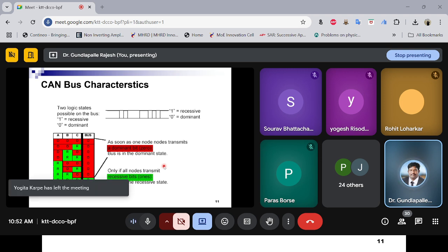So when it is receiving, for every 5 bits it will see the repetition and remove the sixth bit automatically. That is what we call dominant zeros or dominant ones. That is the characteristic which I am dealing with.